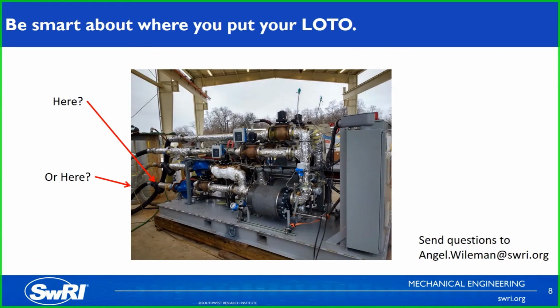And one other thing touching on that, this is a good example from the heat engine project, is be smart about where you put lockout tagout. For this test, we had a hot water tank that was pretty close to boiling, and we had initially, from the P&ID, put the valve right at the heat engine before a hose that was attached to the tank. So when we performed lockout tagout, you still had to disconnect the hose, and now all the hot water from the tank would be spilling out of the hose.